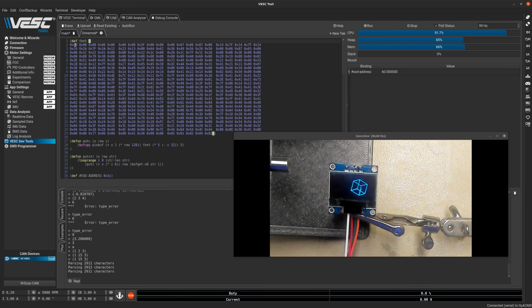And the font essentially means, in this case, this is a small font, so this is constructed with the assumption that when we write it to the display, we have the pixels start from up here, and then count 1, 2, 3, 4, 5, 6, 7, 8, next byte 1, 2, 3, 4, 5, 6, 7, 8, and so on. Making it that way makes it quite easy, because if you want to write one character, then we can just copy from the font, from the character position to the pixel buffer, and we can copy the number of 5 bytes in this case.